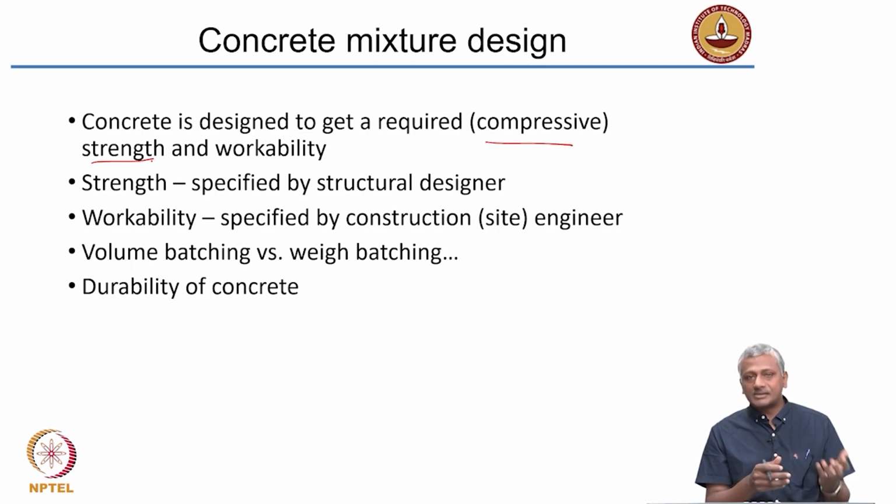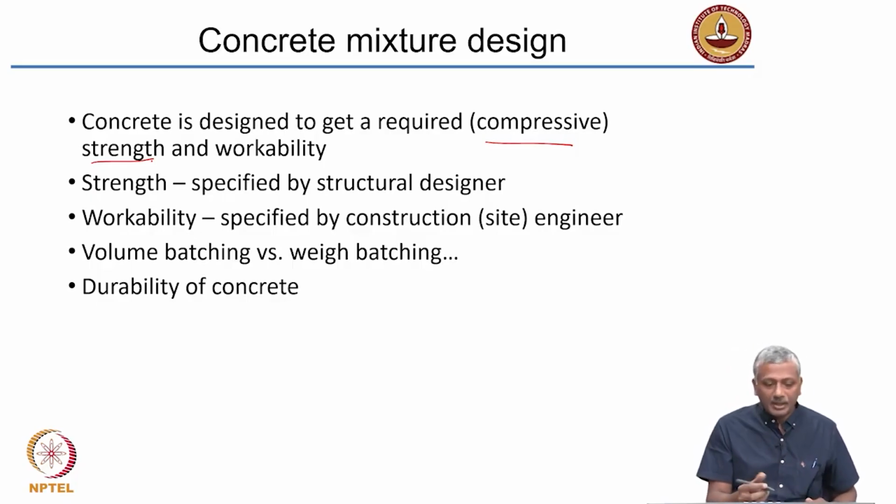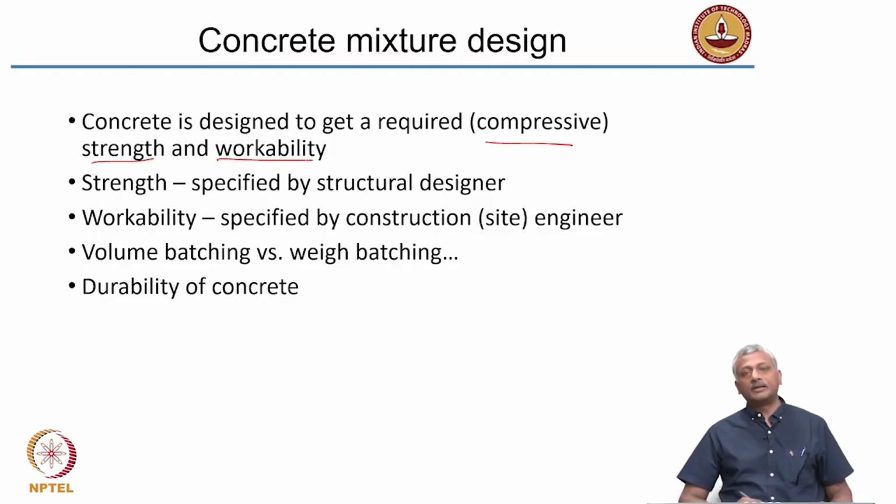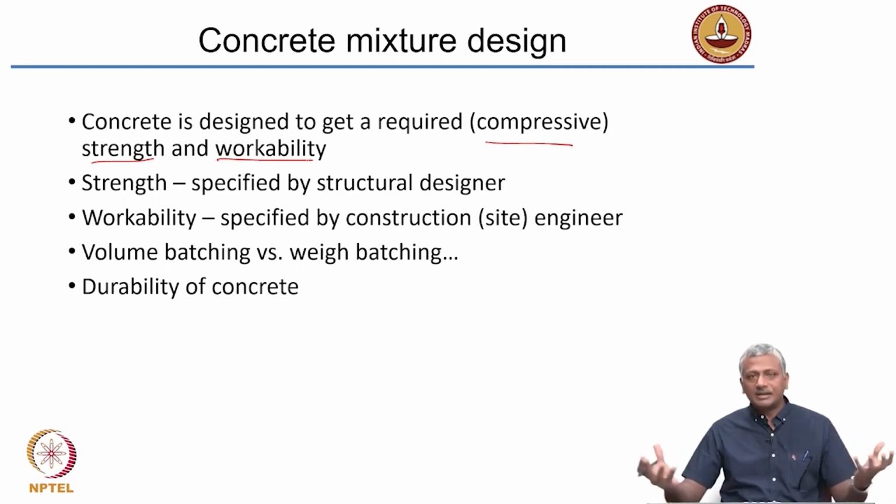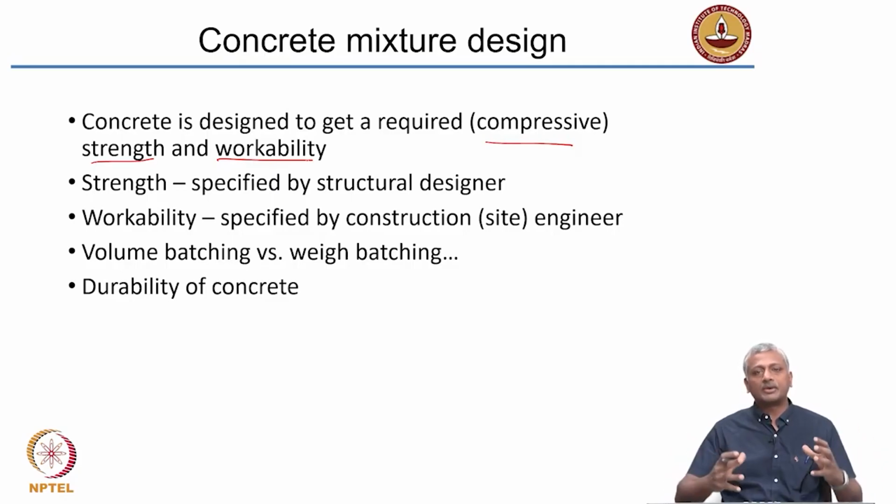In those cases, tensile strength is also considered to some extent. But in most cases, concrete compression strength or compressive strength is what you need to design for. Okay? And the other aspect is the workability. How easy is it for you to mix, place, compact and finish the concrete? Okay? So workability is a term that loosely defines all these processes coming together. We'll take a look at these individual processes separately. Okay? So concrete has to be designed to achieve a certain level of workability.